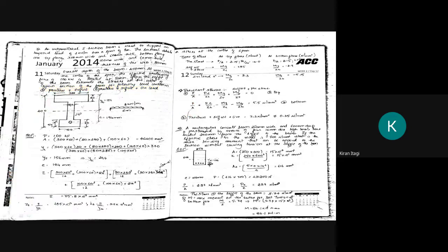Now, the most important thing is that you have to draw the figure up to the given dimensions. So he says that the top flange is 300 wide and 60 thick. Okay, and web he has given. Okay, this is the web. He has given how much? 80 thick. Now, the bottom flange he has given how much? Sorry, 60 thick and 100 wide. Correct? And he has given the overall depth. Now, we have to represent it. Then we have to determine the neutral axis. Okay. For rectangular, if it is 300, then it will be 150 and this is 150. But in case of unsymmetrical sections, we have to determine the neutral axis. Okay, that is this line.